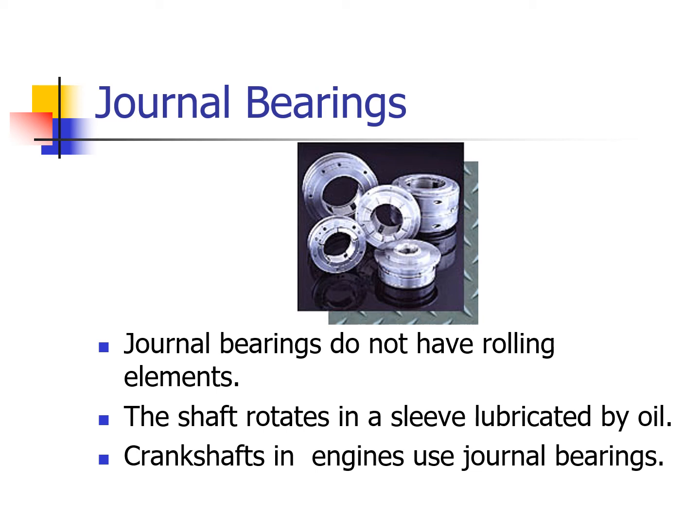And the reason for that is because, again, these journal bearings are a sleeve lubricated by oil. When your car is cold, the oil is thicker, right? And as such, it doesn't flow perfectly well through the bearing. As the car warms up, then the bearings are well lubricated, and that's why you should not abuse your poor car engine until it reaches operating pressure.